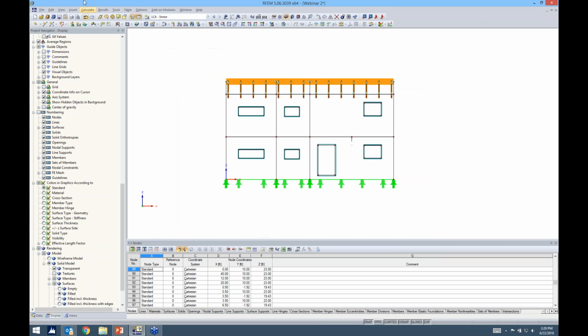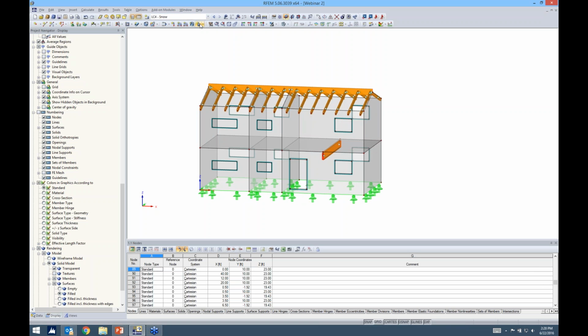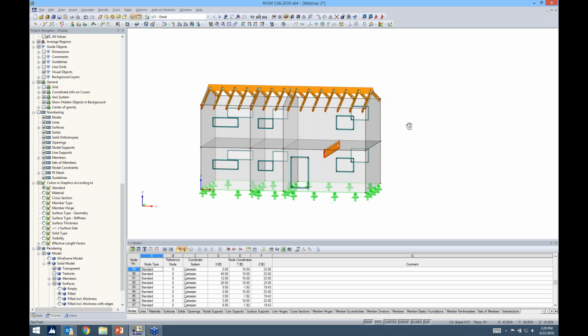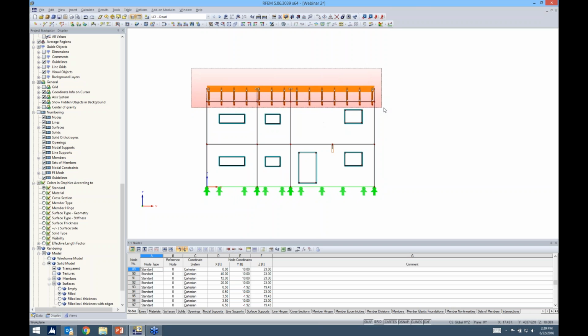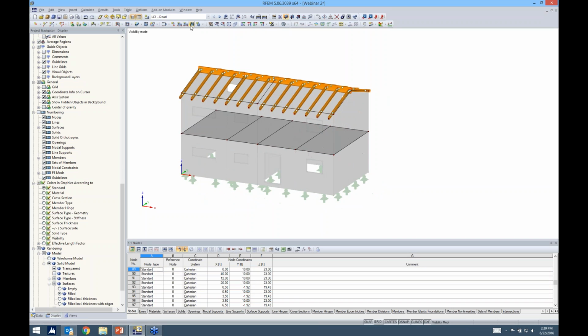Okay, so I can click OK out of here, and you'll notice that when I'm looking at my drop-down box now, which previously was empty, I now have all of my load cases, and then the program went ahead and automatically created all of my load combinations according to ASD and LRFD. For now, when you're applying loads, you want to make sure that this is set on the correct load case that you want the loads applied to. So I think what's easiest here is to go ahead and highlight our floors and make this visibility based on the selected objects. Then I can go ahead and just quickly add surface loads to my first floor.